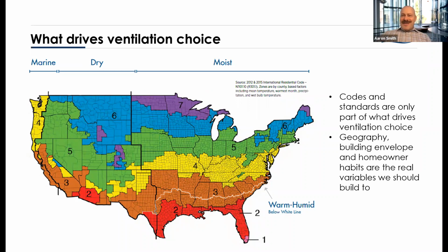Right. Great. And then talk to us about, for those of us up north with our inside humidity currently at 32%, what should we be looking at putting in to get that humidity up to that 40-50% level? So there's a couple different ways to add humidity to the home. If you have a forced air system, that's going to be with evaporative, which I think you said you have, yeah.